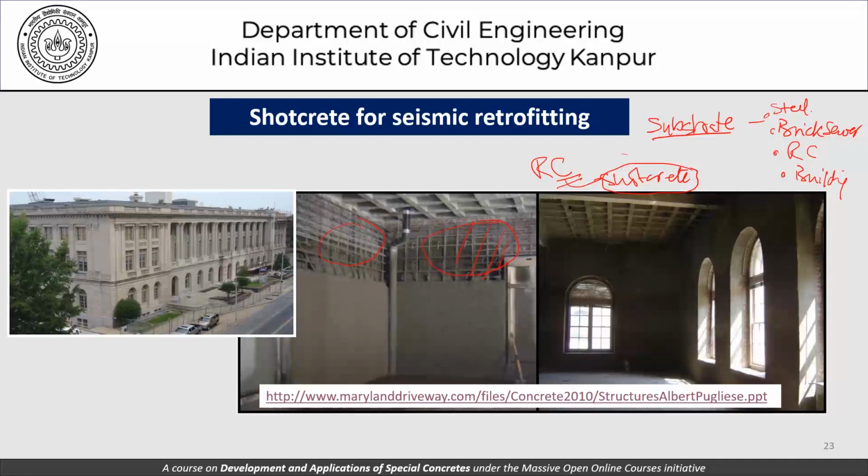This discussion can be viewed in a more or less similar fashion as we talked about fiber reinforced concrete. So fiber reinforced concrete can still be used here as part of this reinforced concrete, and we can also have this reinforcement, which is certainly not fibers. This is normal reinforcement being used in the normal sense, and the concrete being placed using the shotcreting method.